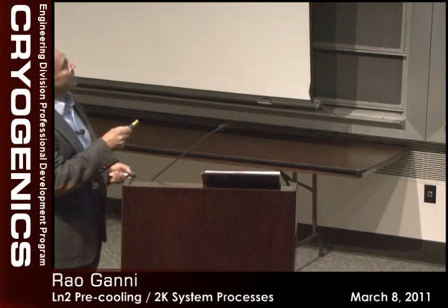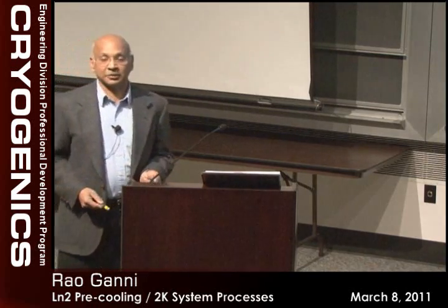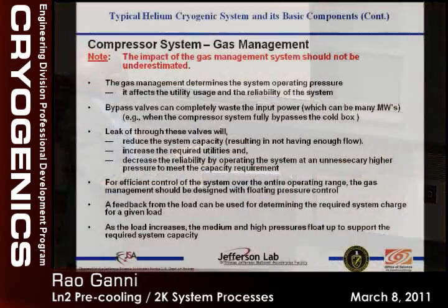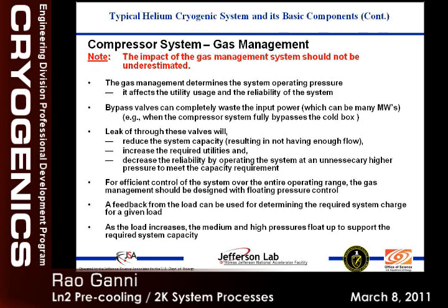Okay. I mean, this is what we went through in the floating pressure challenge. Basically, the gas management is very important. What happens is we set it up, we start it, and the gas valves, everything is tight. But as we operate, there are leaks. And when we size it, we only size it on the first day when everything is 100% tight. But as things get old, they develop leaks, and you have to anticipate all of these in your designs so that no simple small thing is asking you to go for maintenance. You should be able to allow a certain amount of all these things in your plans so that your interval between maintenance can be longer. Like we got, say, 5 years, because so many things have been planned for how to address this in between.